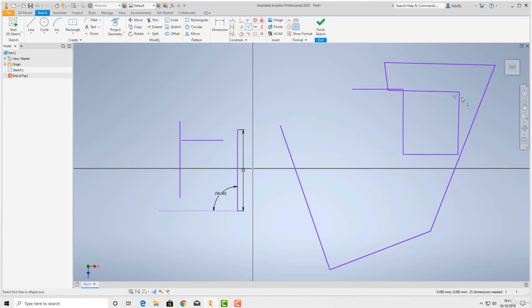Okay. I'll show you this. Okay, Inventor, again, it tries to guess what it thinks you want to do. So it's making them perpendicular, but it's moved the wrong line. We wanted to keep that at the angle. It's guessing that we wanted it to be horizontal and vertical. But what we can do, if we undo that, the reason it's done that is because this line isn't fixed.